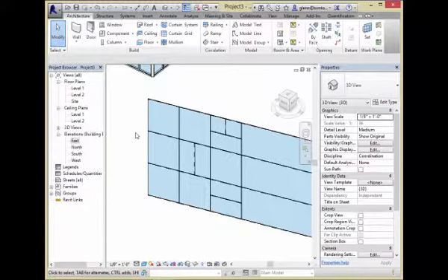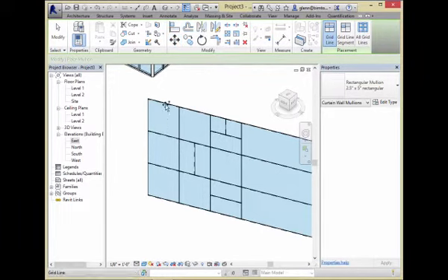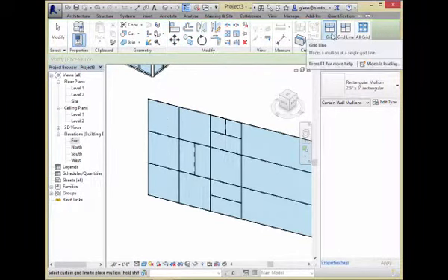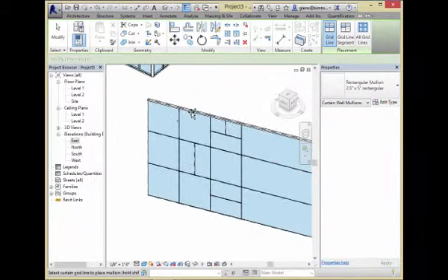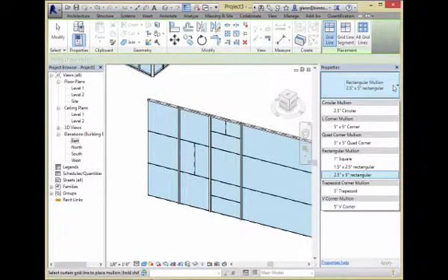Okay? If I want to add the mullions, there's this mullion tool which lets you do that. And I could either choose to add things along a grid line, a specific segment, or everything. So you might start by just adding it to specific lines. We could actually apply different types of mullions, different sizes and dimensions, round ones versus square ones, different kind of lines within there. We can really build it up however we want to.